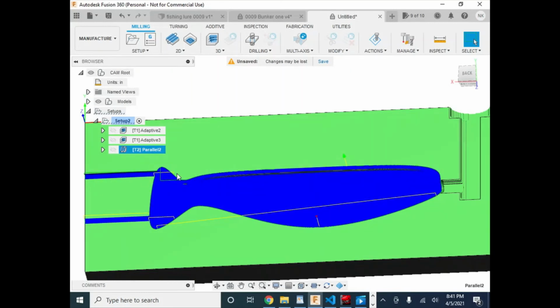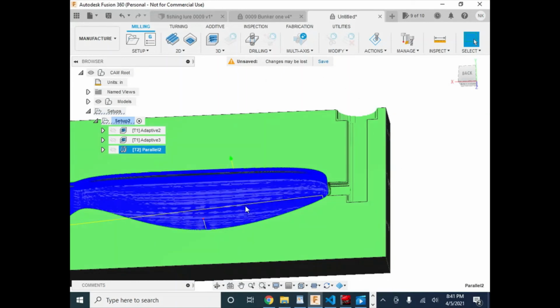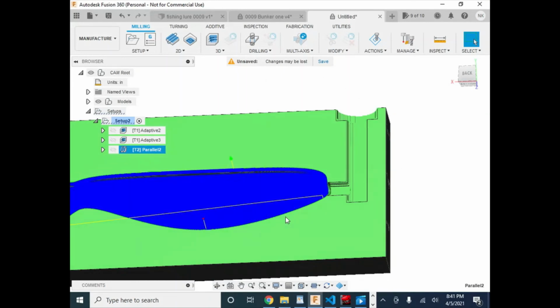And you can see there's really not much tool lift. These yellow lines are the tool lifting off the part, so it's doing the majority of its time in the part. Then what we're going to do is do the same thing to this, except I'm going to change it going vertically because it's a little easier, and we won't care about it having a million steps because it's not a finishing pass. You won't see this. This is just for the injection itself.